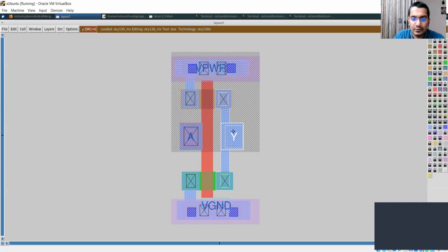The next step immediately after this one is CMP, which is chemical mechanical polishing. We'll remove the extra tungsten that we have over here and planarize the surface. Okay, so this is how your surface will look now. And the further steps are again pretty simple. You need to use some mask and photolithography techniques to bring these contact holes outside your chip. So let's see how we do it.